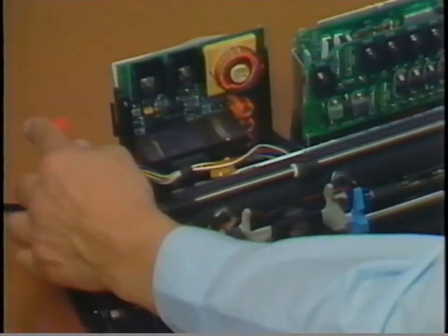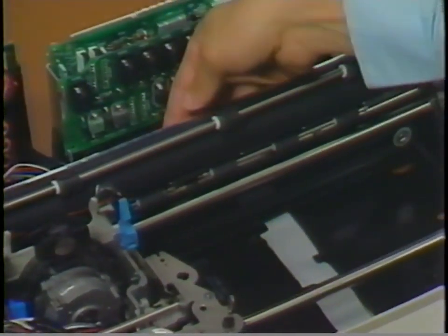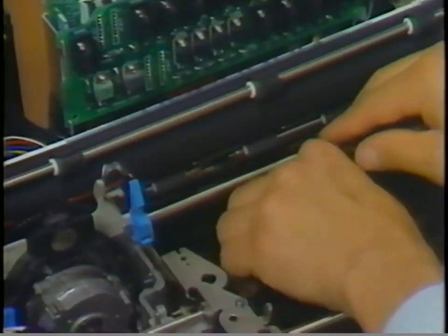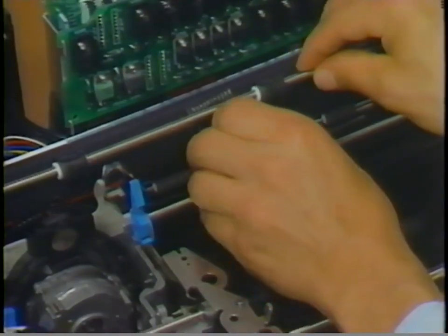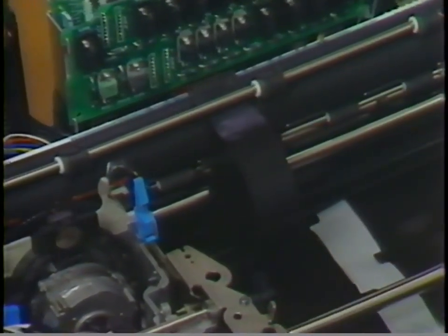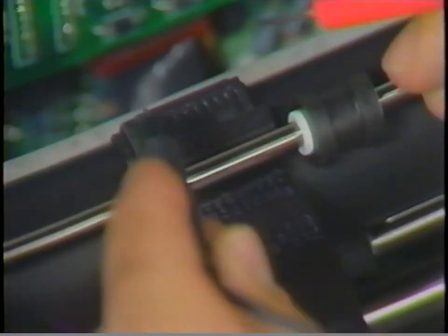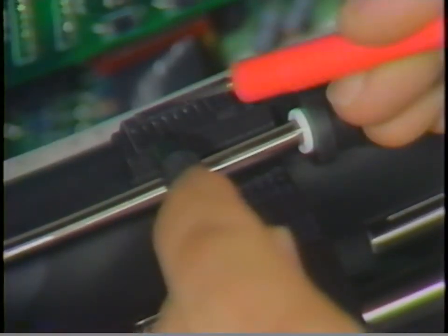The selection motor resistance check is done through the carrier cable. To perform the resistance check of the selection motor, unplug the carrier cable. Carefully zero your meter, and then measure from pin 3 to pin 6, SA+ to SA. The resistance must be from 4 to 6 ohms.